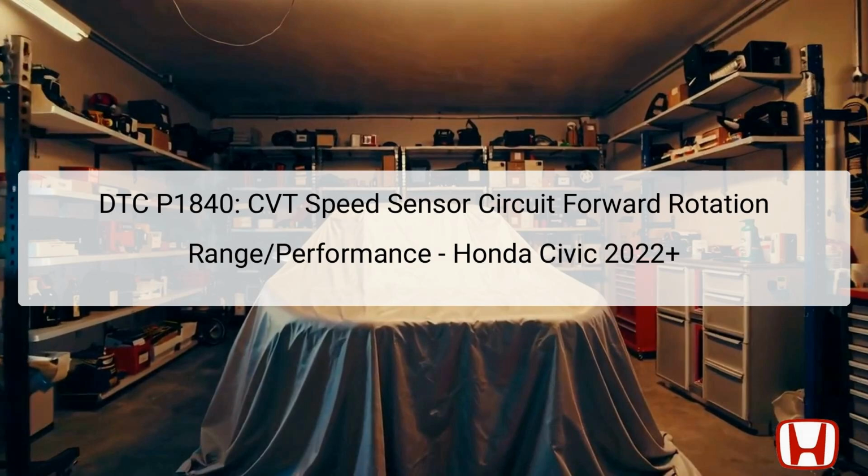When the detected voltage levels from the CVT speed sensor do not match the expected values, the Transmission Control Module (TCM) identifies this discrepancy as an abnormality and stores the DTC. This code may alert drivers to potential performance issues, which can manifest in driving behavior, including hesitation or erratic shifting. Understanding the components involved is crucial for effective troubleshooting.